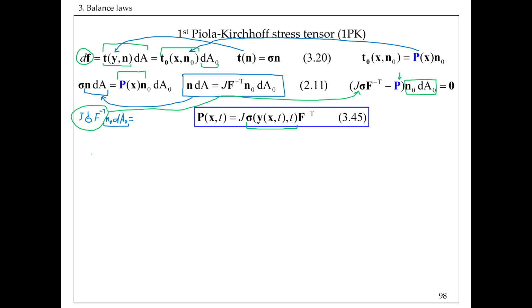And in a way, you can think of a very simple example, when the orientation doesn't change, when you do uniaxial tension. In small deformation that doesn't really matter: you just measure forces, and then you calculate the area that initially was there, the diameter of the sample that you pull, and then your sigma is that force that you measured divided by the area.